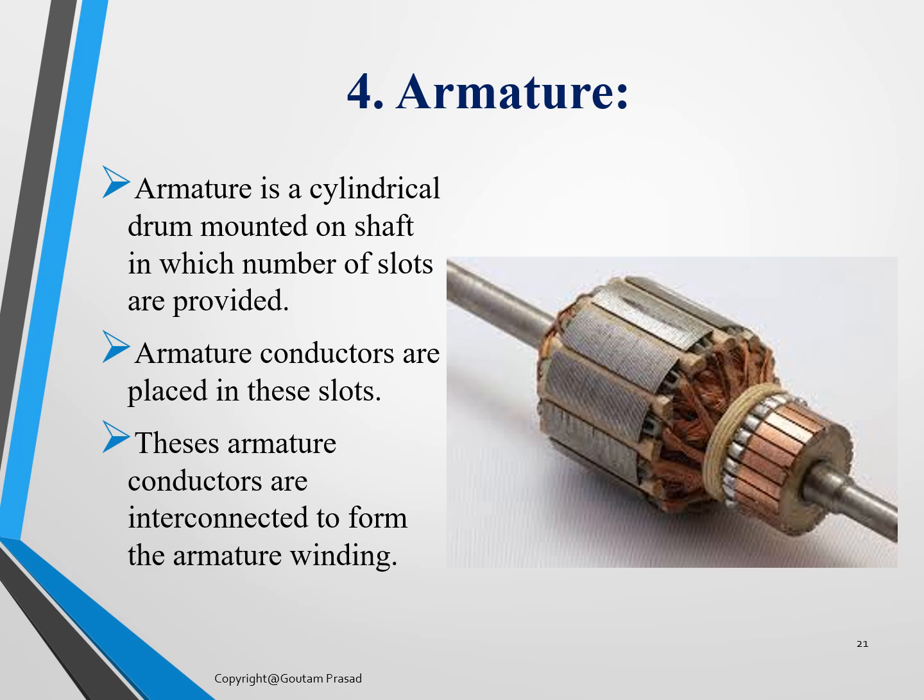Now, armature. Look at the armature as shown in the picture. Armature is the cylindrical drum mounted on the shaft, in which a number of slots are provided, and armature conductors are placed in these slots, and these armature conductors are interconnected to form armature winding.